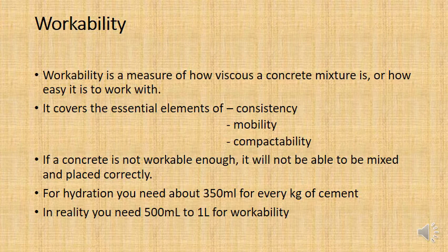But if you were to make a concrete with just 350 mils of water for every kilogram of cement, it will be really thick and unworkable. In reality, most concretes will be anywhere between 400 mils to about 1 litre of water for every kilogram of cement, depending on what kind of concrete you're trying to achieve.